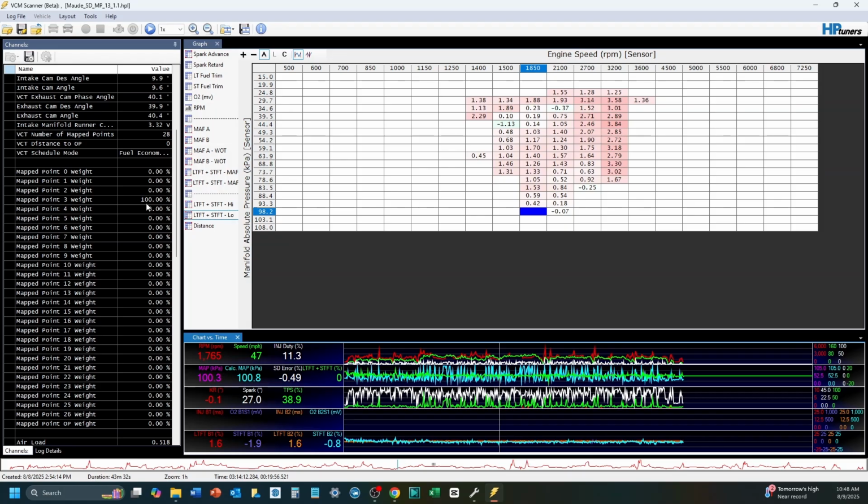And so let me take a minute on that as well as the LTFTs. So I leave my LTFTs on. I've noticed that the ECU is more than capable of calculating that, and that the percentages I get in aggregate I'm able to apply to my tables, and I'm getting fairly good results. If you are not seeing results, the old school tuning method and the right way, in quotes, is you could turn your LTFTs off and govern just against your STFTs and use those to dial in. That would work as well.